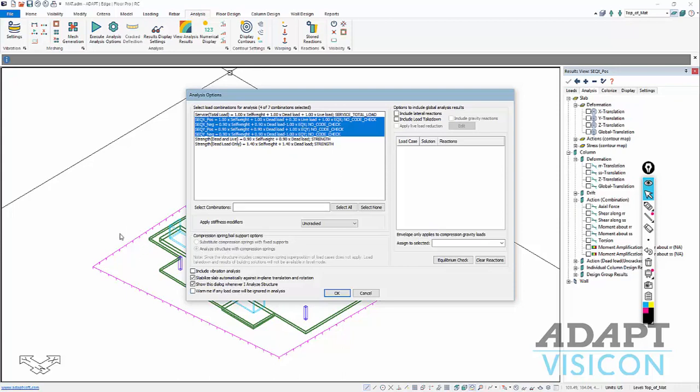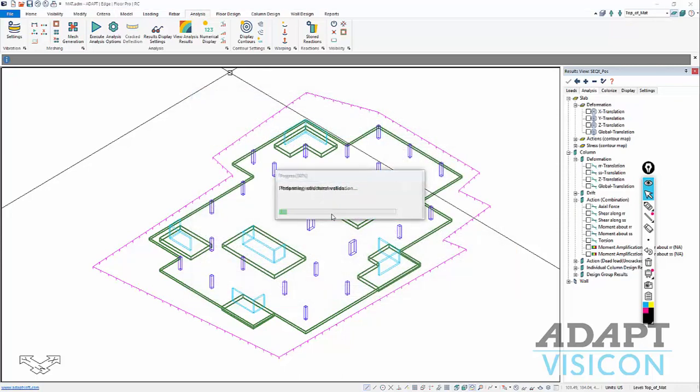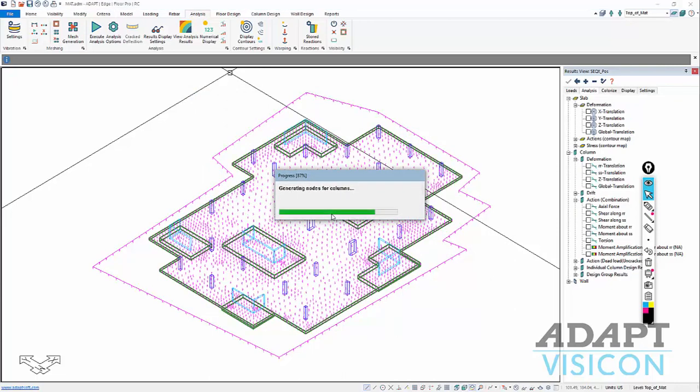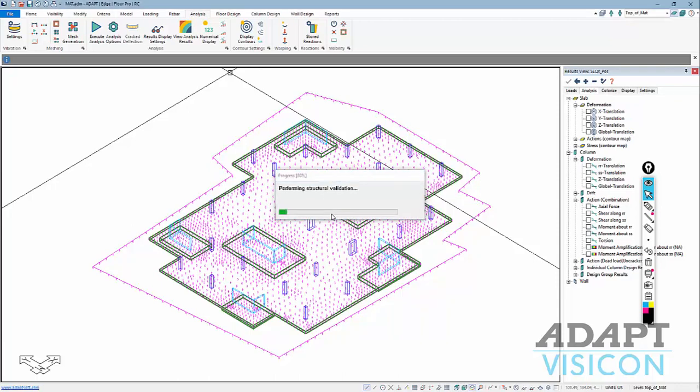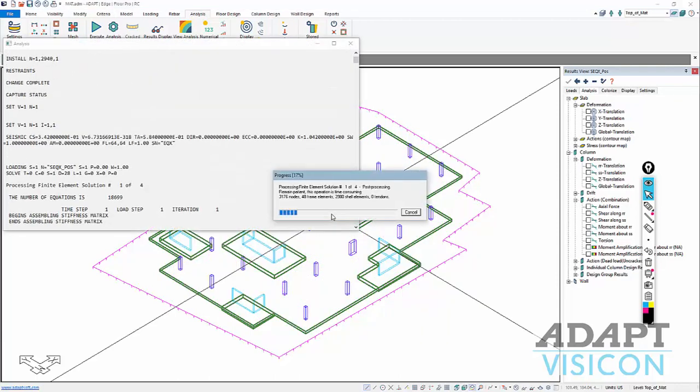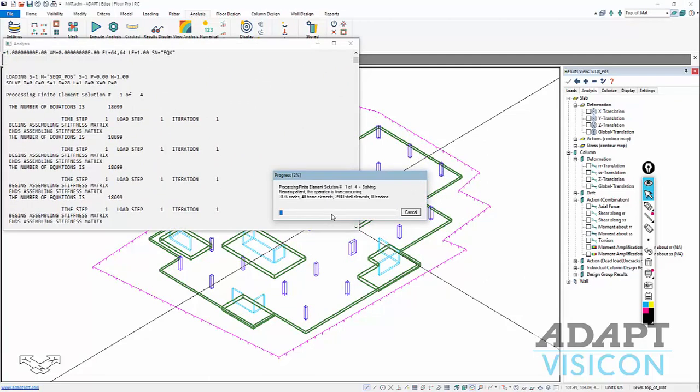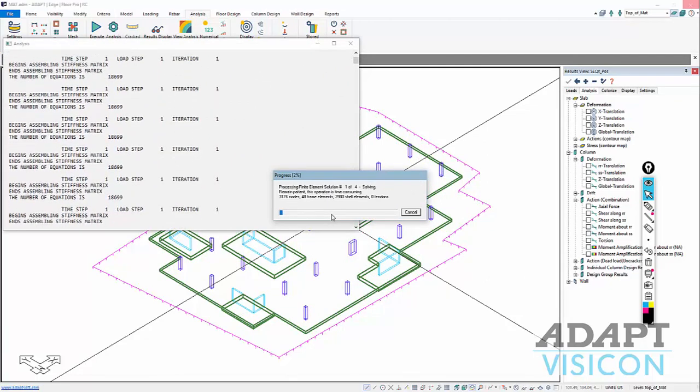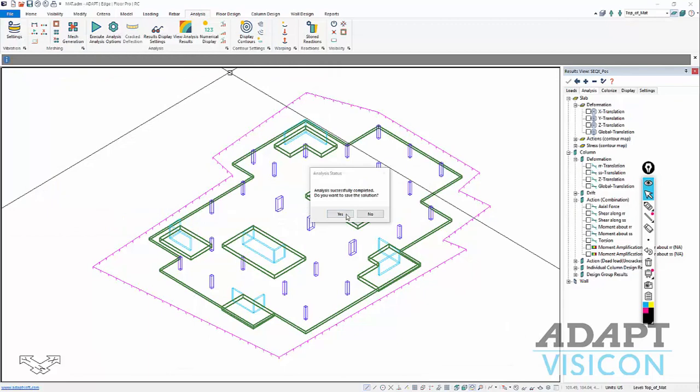This will inherently capture the participation of the springs because the springs are modeled in the single level, and I'm going to include the reactions for lateral and also gravity from the FEM global solution that I just ran. And now I'll just rerun this level with those reactions, and then I could evaluate soil pressures and different results required to check serviceability and strength requirements of the mat. We could generate reinforcement by use of strips and so on. We'll save that,